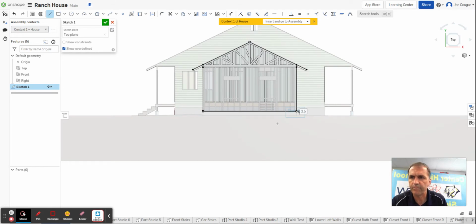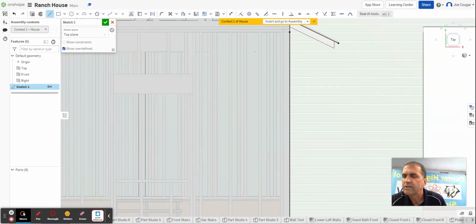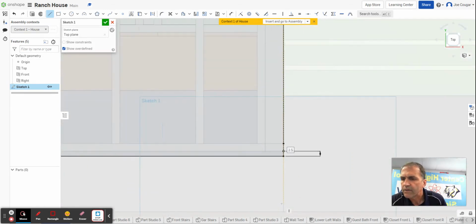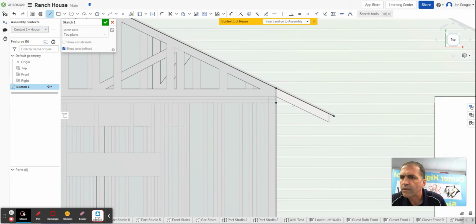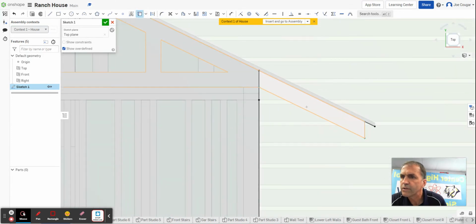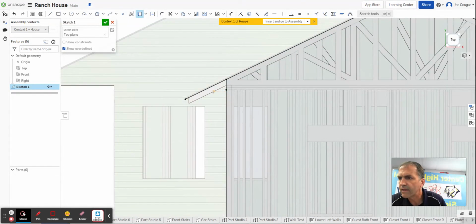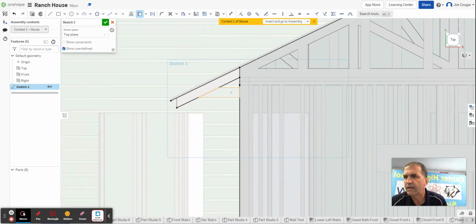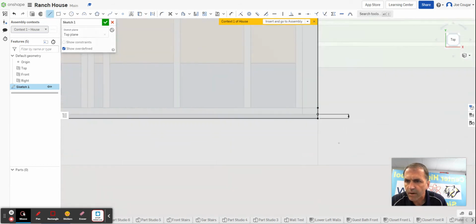Now, I'm not done yet, because before I extrude things, I want to go ahead and make it so that I can draw in the side profile of the siding that's going to go down the sides. So here's how this is going to work. Well, first I have to use some edges. So we're going to zoom way into here and I'm going to use that edge, and same thing on the other side, that edge.